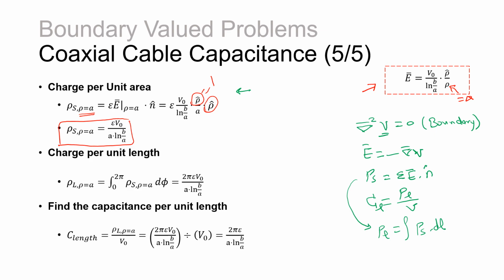Now, as I have said, we can calculate rho L by a single integration, but we need to think where this single integration should be done. Let's draw the inner conductor. It is something like this. Unit length, then we will be moving in the z direction. But we are staying at a single point here, so we need to care about the rotation here, which is phi.